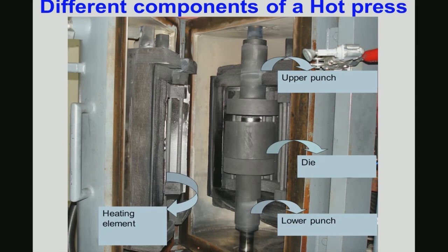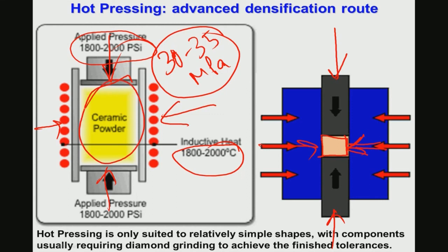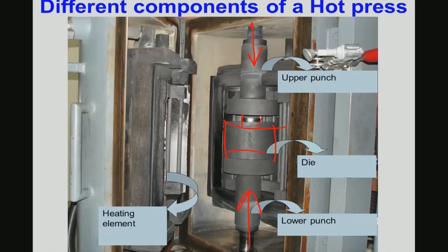This is the classical hot pressing unit. So, you can see this is the ram here, you apply this compressive force, this is your graphite die punch assembly, and you can see this is your punch here which is exposed outside, and inside the die you have a die cavity, and this powder is now filled up in the die cavity. Then the whole assembly is put under the upper punch and lower punch, then you apply the compression pressure and then the material gets densified.